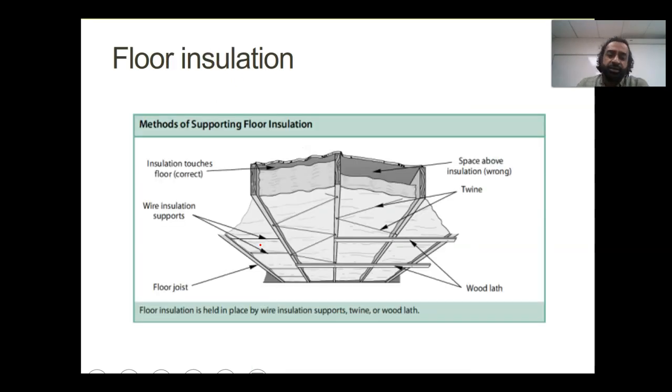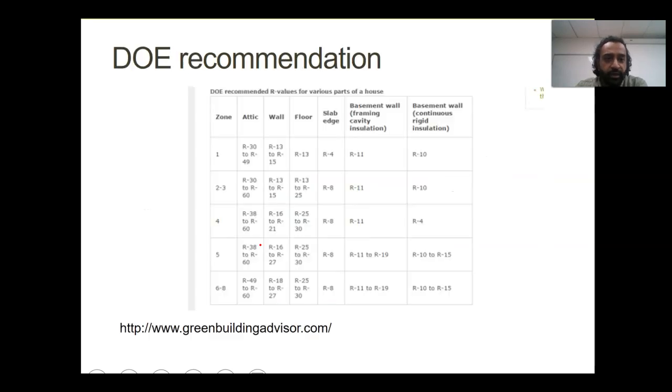This is another idea to insulate between floors. You can use twine to stick batts in the top. As you can see, it's really hard to put foam in here. It will fall back. This is a practical way to put these kinds of fillings inside the cavity for a floor or ceiling. However, you want to keep them in place and keep things from getting into them. Again, mice and moths and a lot of insects like to live in that foam because it's warm and has a lot of cavity. So make sure when you do this kind of barrier that you have the proper insulation to close all these openings so you don't have a lot of vermin living in there.